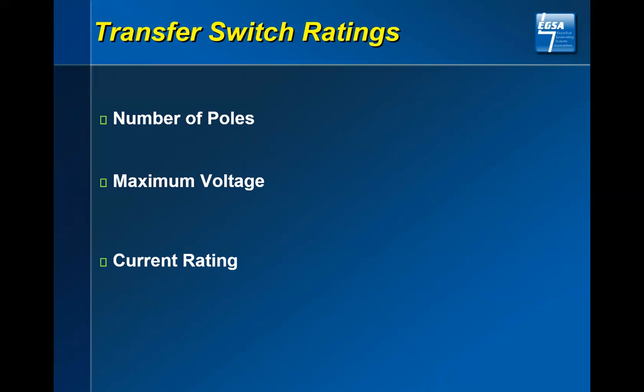There is what's referred to as a 100% rated breaker. I advise you, if it's not making sense, please take a look. It was very easy to Google that and get a little bit better education on it. But in the case of whatever the rating of the overcurrent device, typically a circuit breaker upstream, if it's a 600 amp, I must have a 600 amp transfer switch.